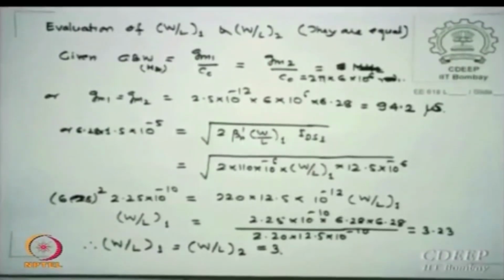The reason why the lower transistors should be smaller than the loads is the capacitance effect they hold. This is a P channel device, this is an N channel device, so matching is needed: the N channel device should be smaller than the P channel device for the same currents to flow through.